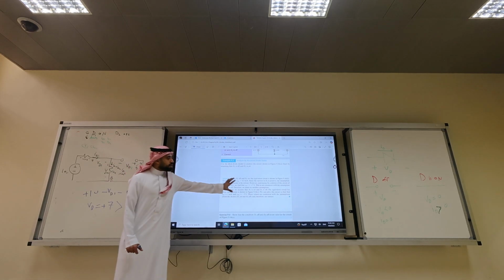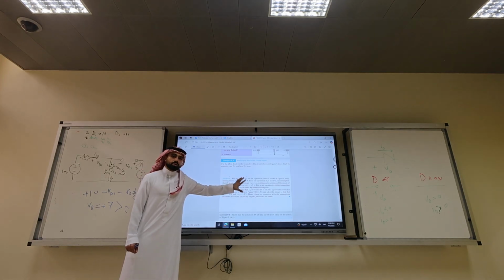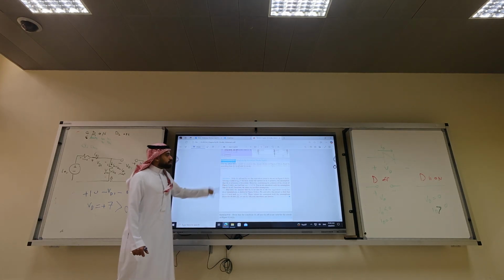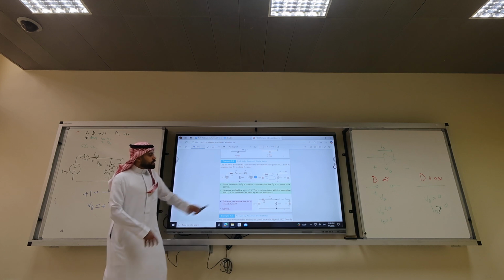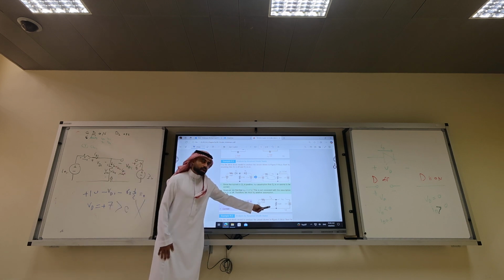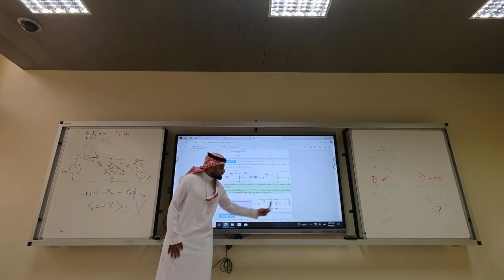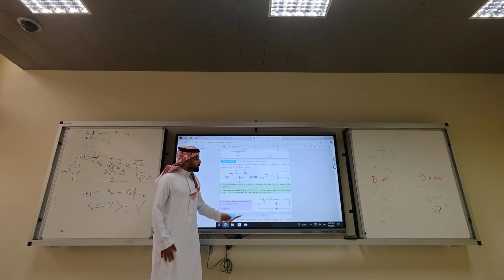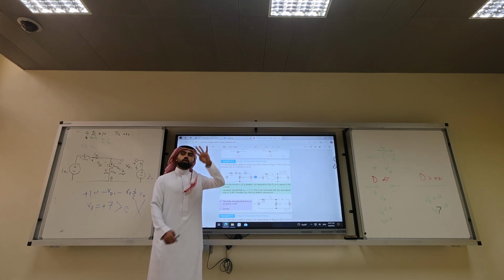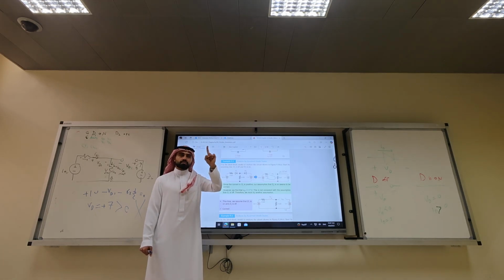Now this is written explanation of what we just explained. Let me repeat one more time. Is this circuit correct or this circuit correct? The second one. Can you calculate the current immediately? Yeah, it's 10 over 4 plus 6. It's 1 milliamp. Then you need to go verify all the 4 conditions. If one is violated, the circuit is wrong. Go to the next assumption.